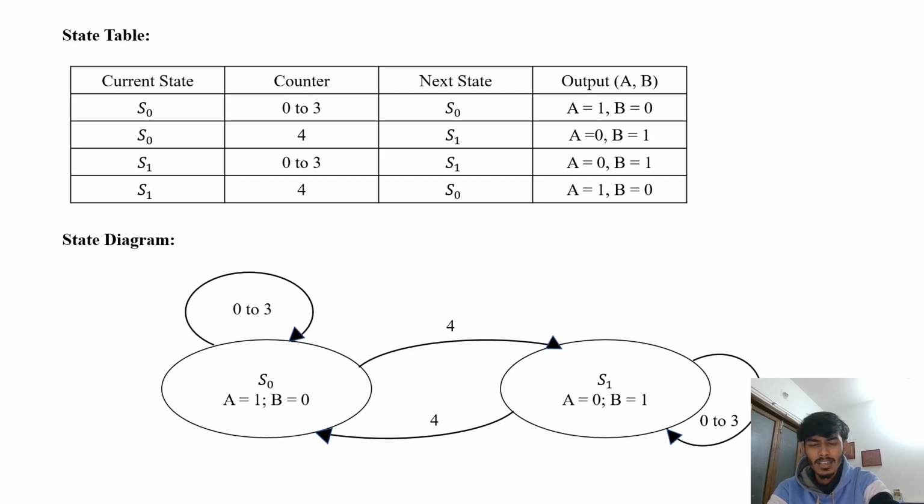In this slide, the state tables summarize how the system behaves for different ranges of car counts. It clearly shows which display activates at which count, making the design easier to verify. The state diagram visually represents the same behavior. It shows how the system transitions between the space available state and the full state depending on entry and exit sensor events.